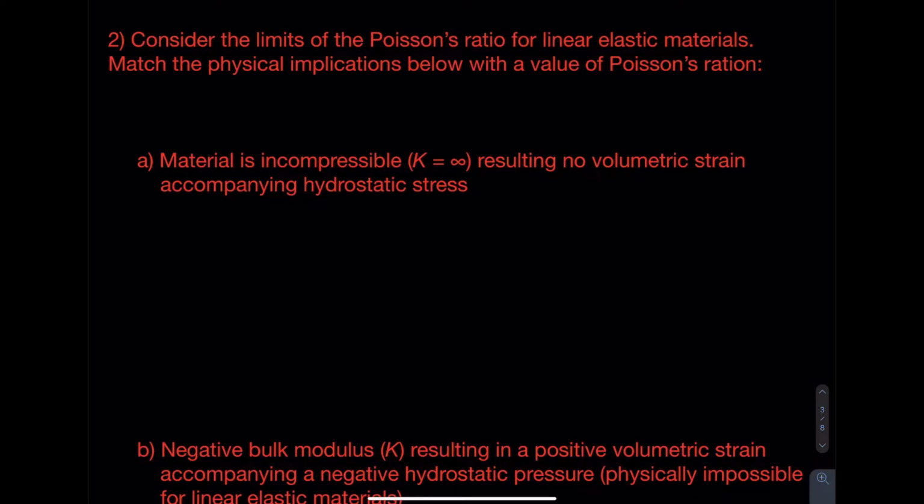However, right now we're just considering the Poisson's ratio limits for a linear elastic isotropic material. We're going to discuss each of the scenarios and where these limits come from. Right above here, I'm going to talk about the limits. We know that Poisson's ratio must be between -1 and 1/2, and as we come down here, we're going to derive these limits a lot of the time.